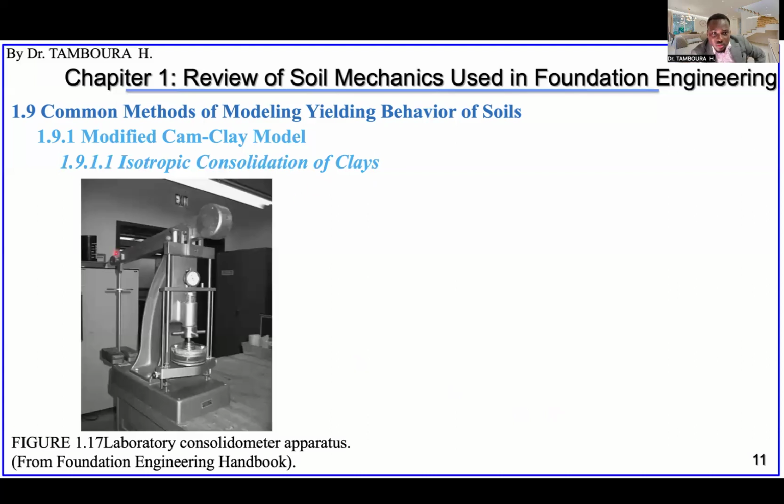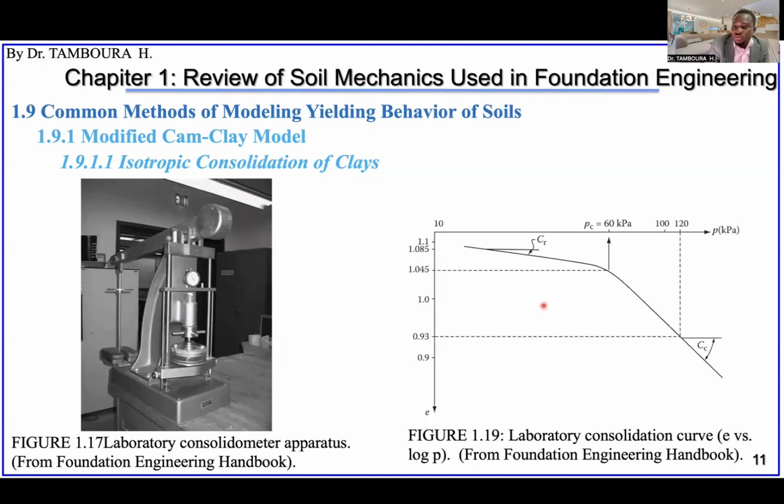You remember this apparatus, the one-dimensional consolidation test for clay. I don't remember which video, the number of the video, but we did this before. Going with this to help us know the recompression and compression index. And this is the pre-consolidation stress. I hope you remember.